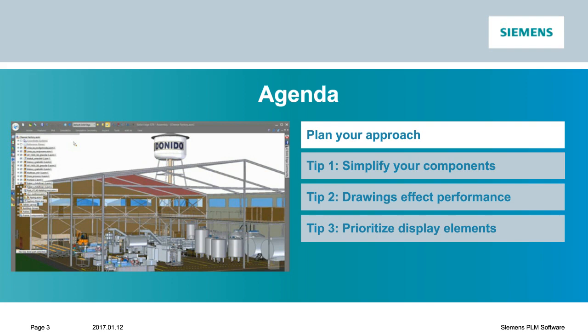One of the things that Ken mentioned that I want to mention again is the use of templates to standardize company information. So you might have a lot of metadata that you want to see in various places associated with your parts. And the best way to do that is to have start templates that have that metadata already built in so that you don't have to count on users remembering to enter it every time. Using templates is a great way to do that.